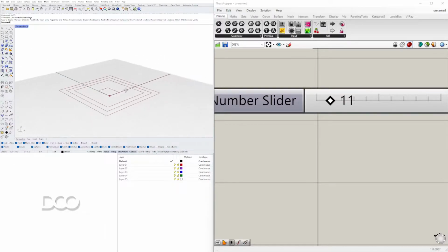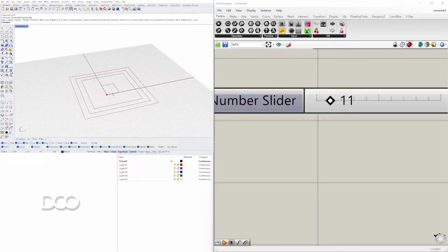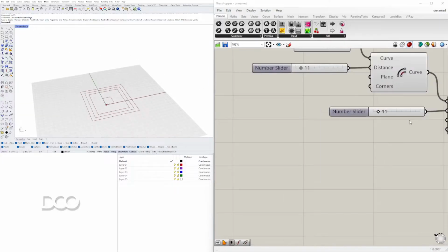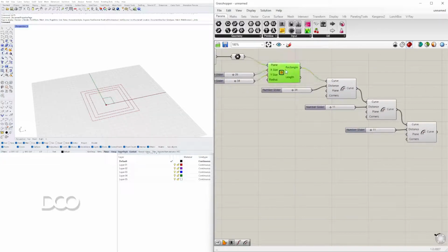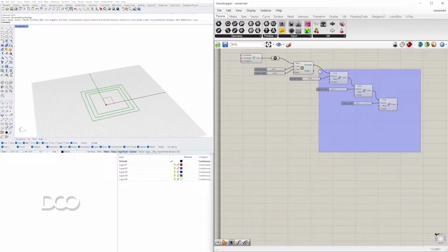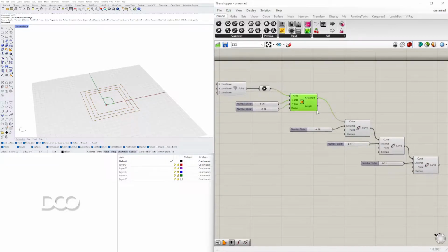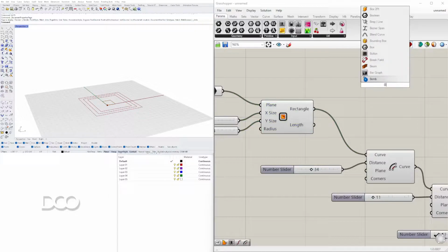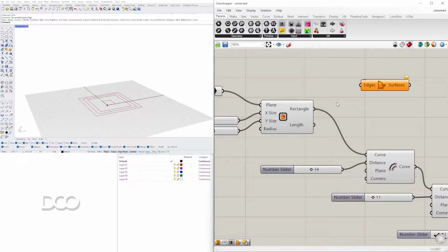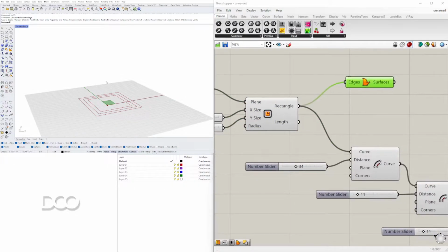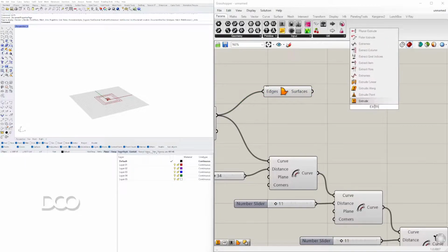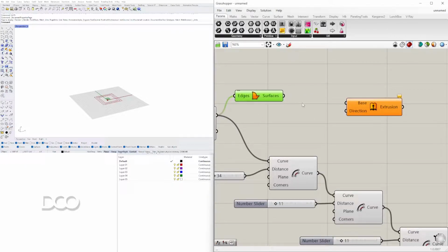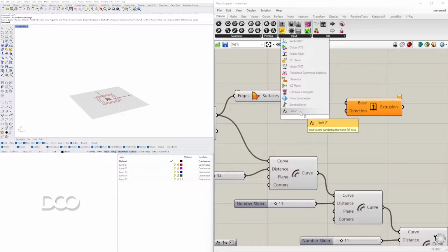And so for now, let's start by creating the elevator tower. What we'll do is we'll go here back to our rectangle. Now we're going to turn this into a surface. So I'll double click here, go to boundary surfaces. And now we can extrude this to a specific height. So I'll go here to extrude. In which direction? Unit Z.